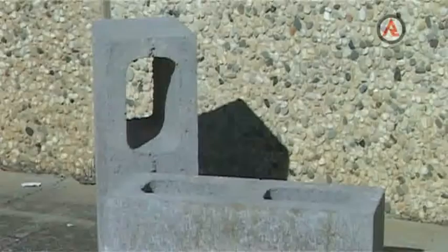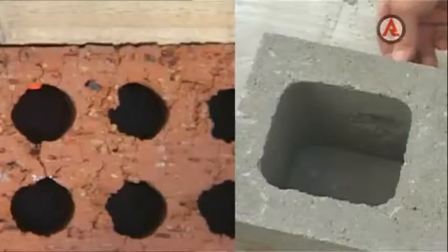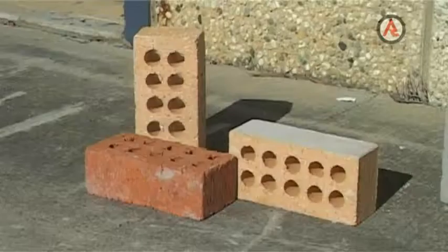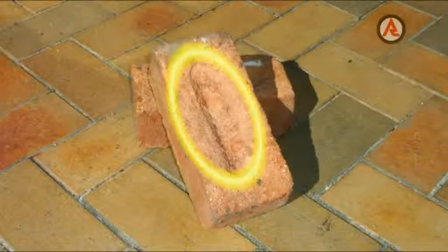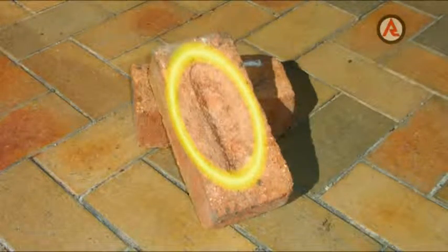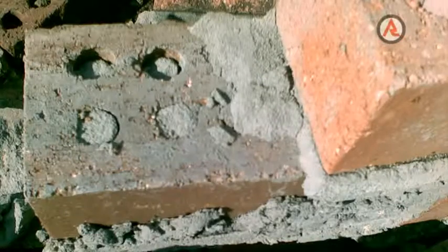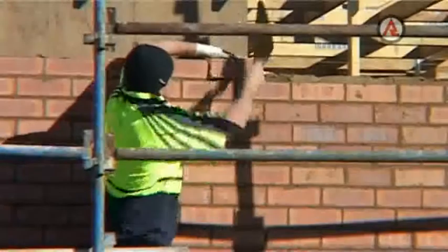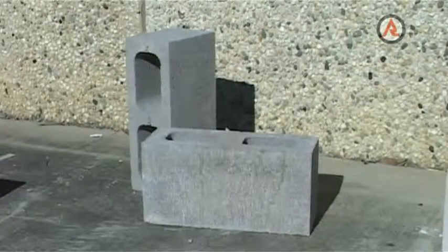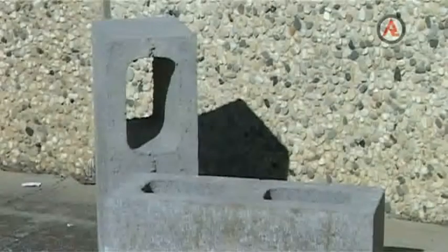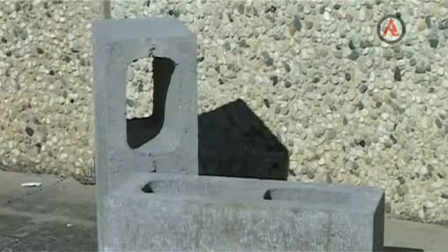Bricks and concrete blocks could have either a solid or hollow center. Most bricks have holes through the thickness of the brick, replacing what was known as the frog of old-style bricks. The holes act as a key, allowing the mortar to flow into them, forming a strong bond between courses. Concrete blocks are usually hollow, saving weight and the amount of material used to make the block and providing some degree of protection from the passage of water through the block.